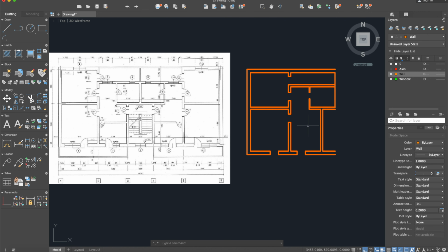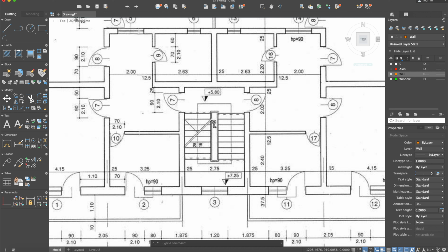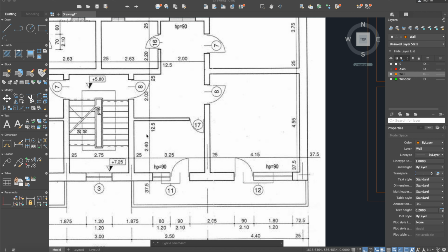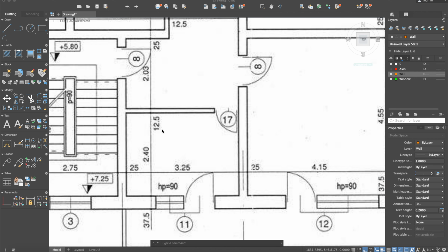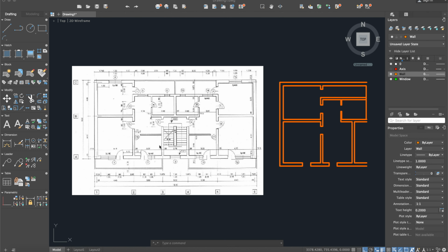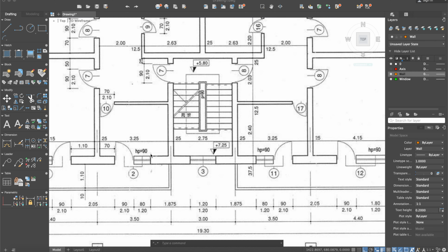They start to look pretty much the same, but here, as it can be seen, we have another wall. So we must look at the other side here. So this part is 240. But at the same time, we can see here that this wall this time it's 12.5. So we will do exactly like this. So we will offset this part with 240.